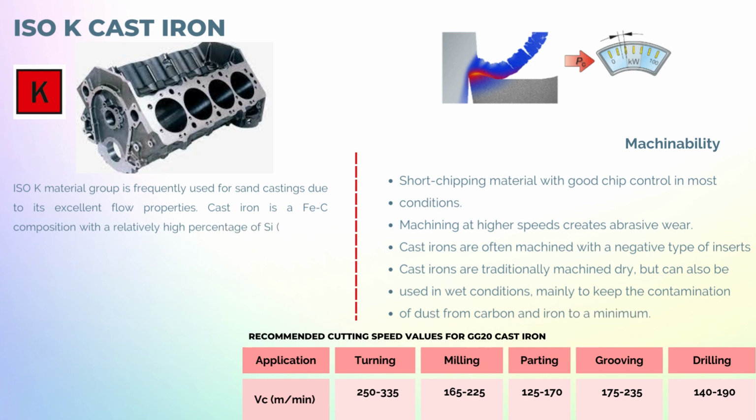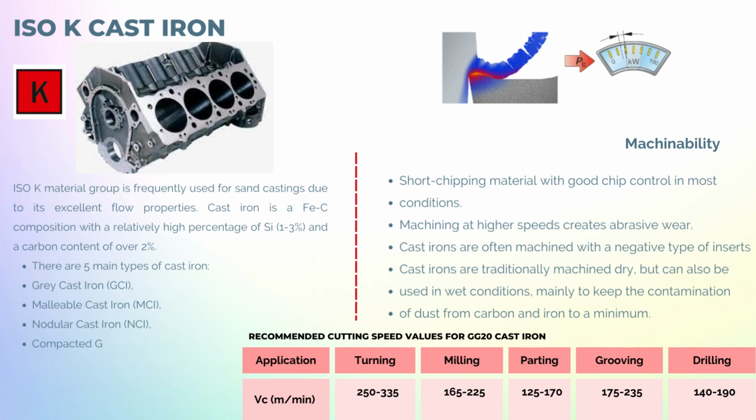They have low melting points, high machinability, lower adhesion and strain hardening, and lower thermal conductivity than ISO P steels. Cast irons have low impact strength, similar to brittle materials, good thermal conductivity, good dampening properties, and ultimately, low hardness.